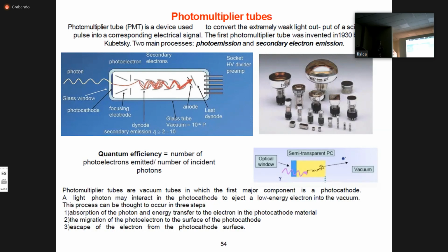And this charge can be processed like in an ionization chamber. You have a capacitor, a resistor, they will give an amplitude in voltage, and the value of this amplitude is pretty high compared to some other types of detectors, and you can use, for example, a simple preamp and feed it to your data processing system.